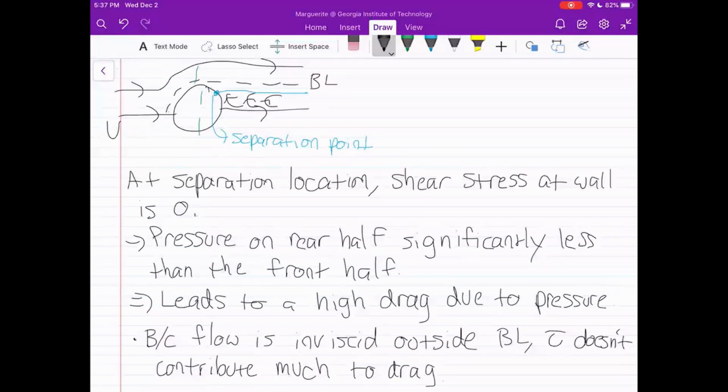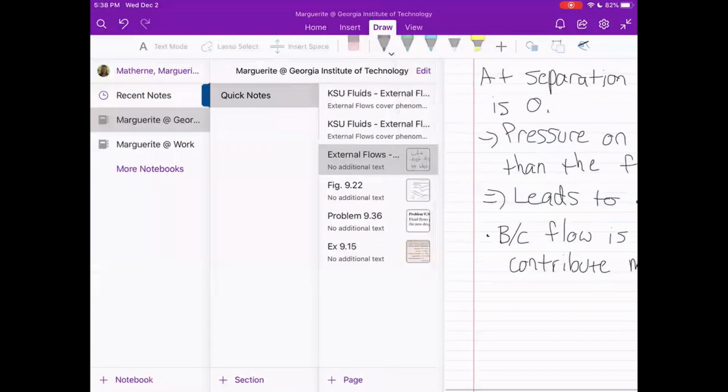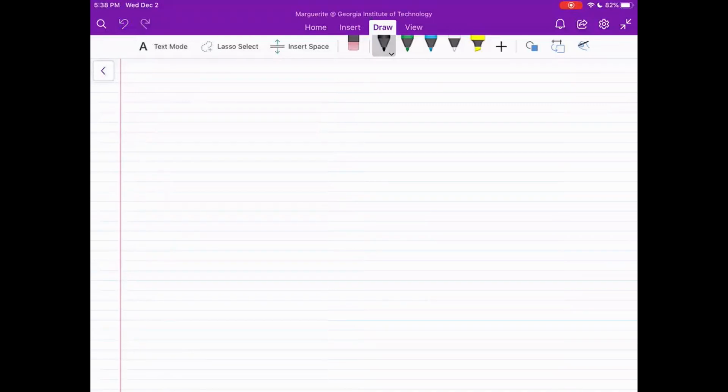Okay. So what we've talked about so far, as we're still in drag, is how the shape of our body and also the Reynolds number of our flow will affect the drag. What's important to note here is that we can't necessarily separate them. We can't say, oh, this is a cylinder, so I'll look it up on this table and it's always 1.5. That's not always the coefficient. You also have to account for the Reynolds number. So they can't be taken as individuals. It's kind of like a composite thing. And so I'm going to go to here. Where is it? There it is.